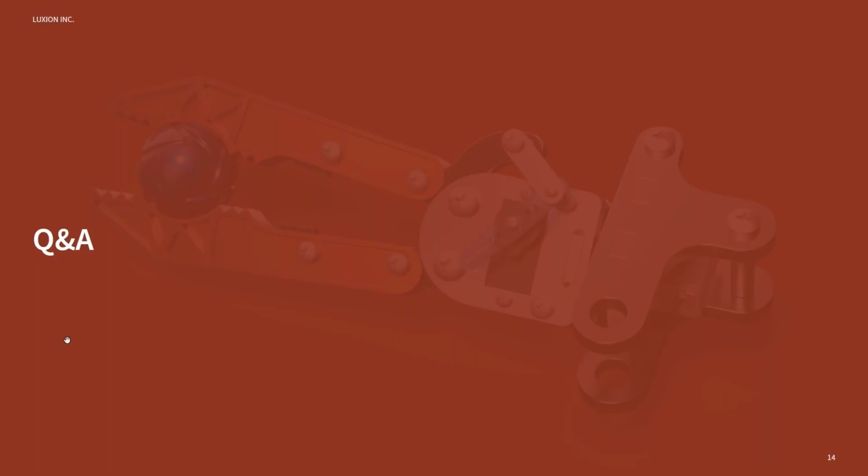Cool. Actually, there is one thing that came to mind for me when working in iterative design, and you're saving variations of SOLIDWORKS files. If you do want to retain the live linking functionality, then the name of the SOLIDWORKS file must be the same.